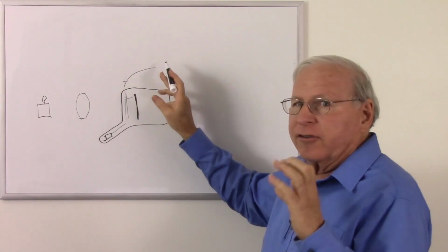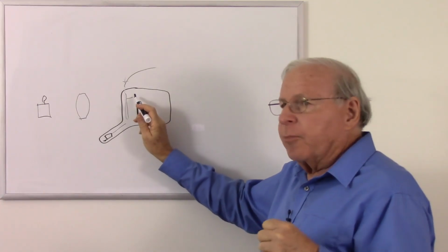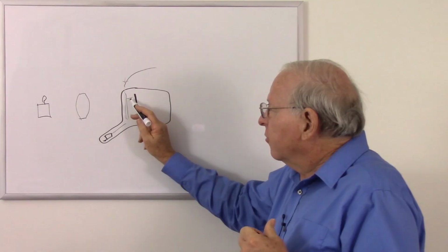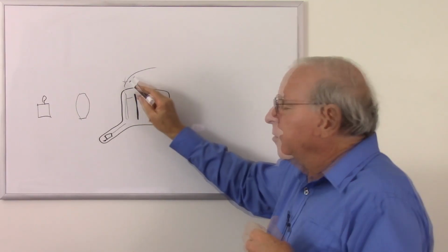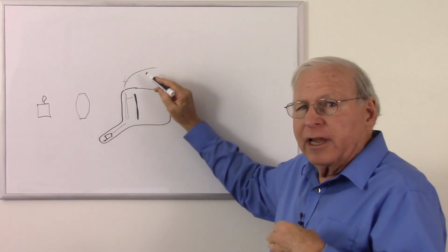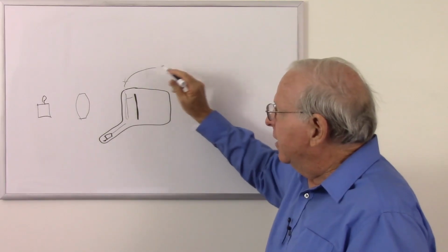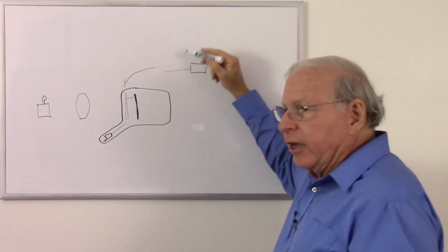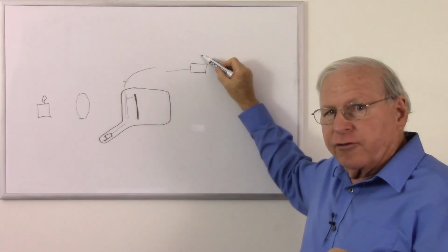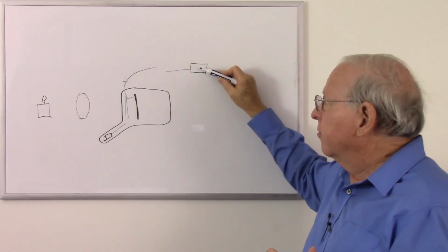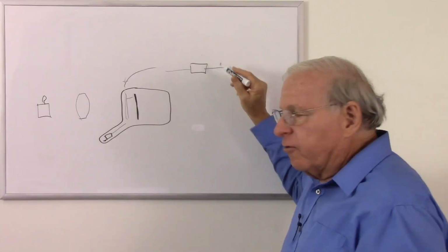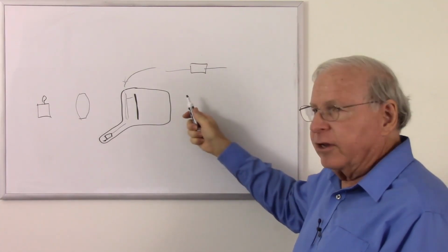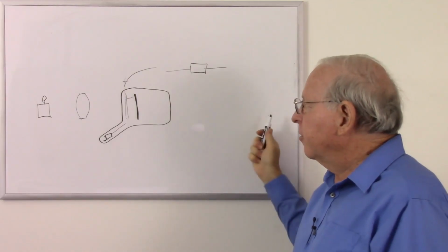So a lot of electrons at dim areas, but at a bright area where a lot of electrons had been removed by the light, fewer electrons would be reflected off, so we'd get fewer electrons where there was a lot of light and more electrons where there was a little light, so basically a negative image. And this information was taken back and processed, inverted, so that we get more electrons where there was more light, fewer electrons where there was less light, and eventually create something that could be turned into a signal that our CRT could then paint our picture back with.